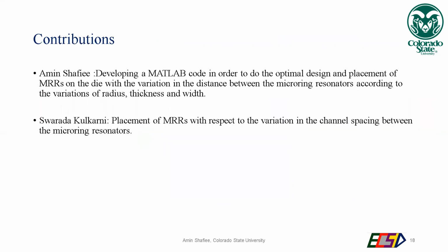For the contributions to the project, Amin Shafi took the liberty to develop the MATLAB code to do the optimal design and placement of MRRs on the die, with variations in distance between the microring resonators based on the thickness, radius, and width variations. And I performed the placement of MRRs with respect to the variation in the channel spacing between the microring resonators.